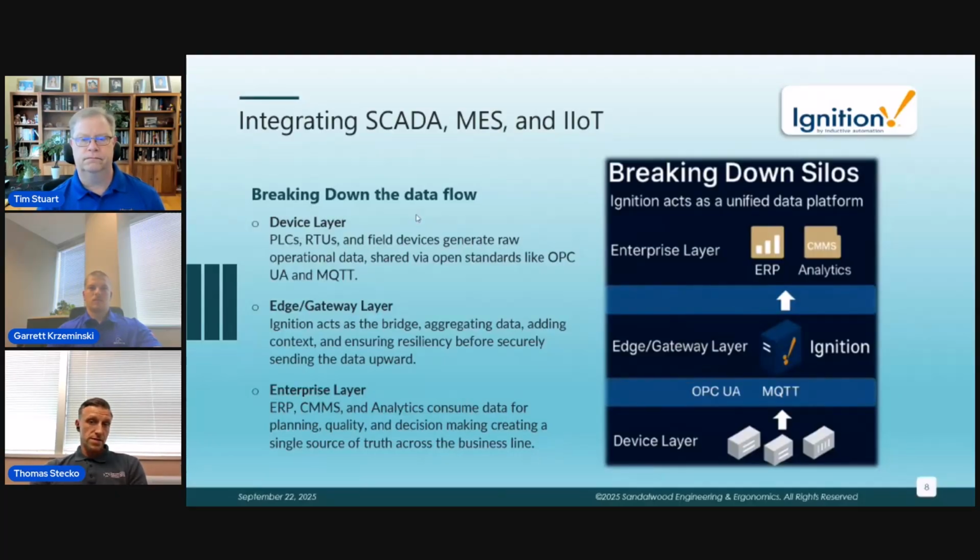And then that data is processed via open standards like OPC UA or MQTT, publish and subscribe services, right? So here an example would be an older PLC that's running on a packaging line that can still feed data into the system once it's exposed through OPC UA.